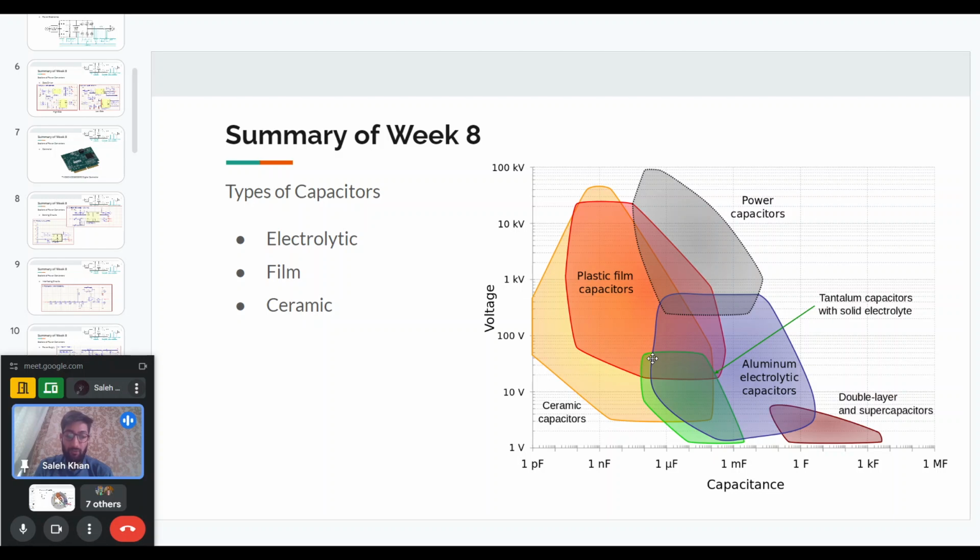And we can also have small capacitors like the snubber capacitors. They will have varying voltages. So the voltage will vary between 0 and the DC bus voltage, and those voltages will change very fast, but the capacitor value is small.